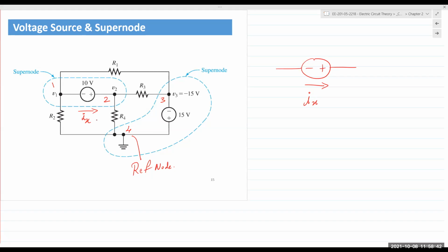It doesn't matter what direction the currents are going, but I can rearrange the expression to say Ix is equal to IR2 plus some combination of IR1. Make sense to everyone? Then at the other end of the source, node 2, I can again apply KCL. I get another expression for Ix. Ix would be IR4 plus IR3. Ix is now equal to A. Ix is also equal to B.